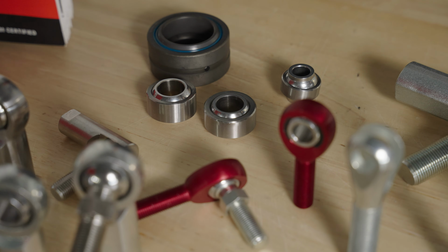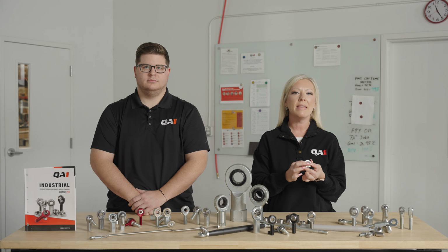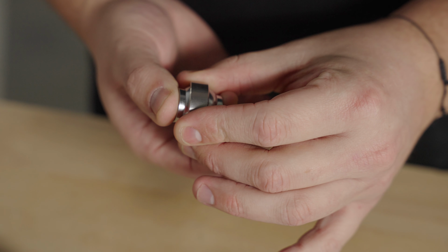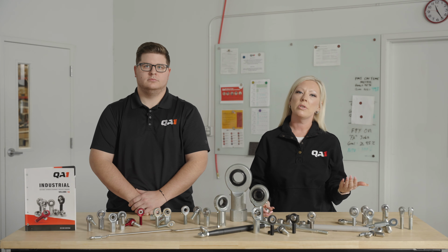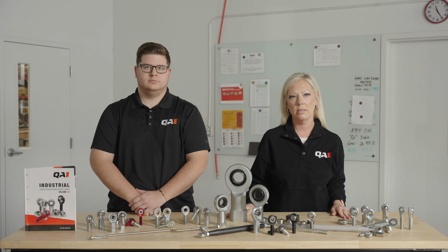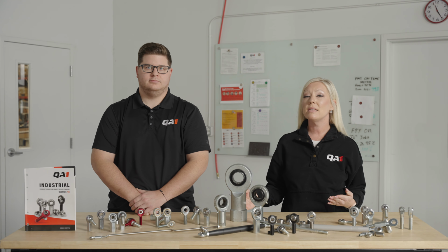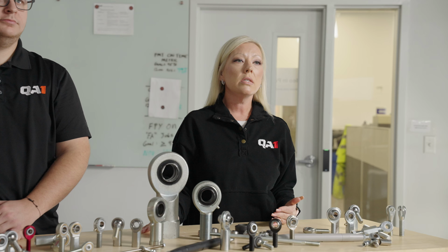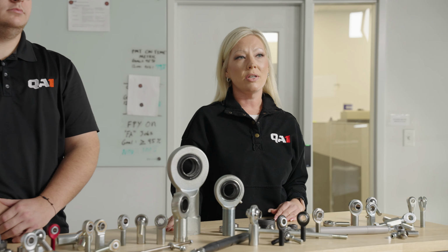Plain spherical bearings are used anywhere a pivot point needs to rotate, swivel, or misalign under load. Because they allow the ball to pivot inside the outer ring, they're ideal for applications where movement occurs in more than just a straight line. Typical applications include cylinder mounts, suspension pivots, steering knuckles, and industrial machinery. You would often use a plain spherical bearing when either the joint needs to pivot inside a fixed housing, or you want a solution that is pressed into a structure rather than threaded on, or you might even need misalignment capability but not an adjustable linkage.